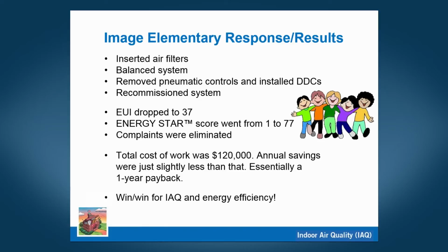The prior number that you saw, 120 for energy use index, dropped to 37. Our Energy Star score went from 1 to 77, and our complaints were eliminated. Again, the whole purpose of showing these slides is we're responding to an indoor air quality concern, and found that we could marry that with energy efficiency. We really haven't had a complaint at that school since.